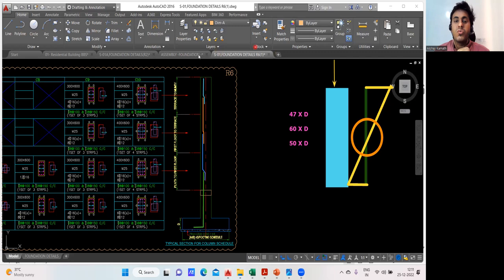So you don't have to do it in that way. Just remember, every floor I'll do one lapping. From here to the top of the plinth, the middle of the plinth, this is one floor, one lapping I'll do. From the plinth to the first floor, I'll do another lapping. From here to the top, I'll do another lapping. So how many lappings will come? Three lappings will come.